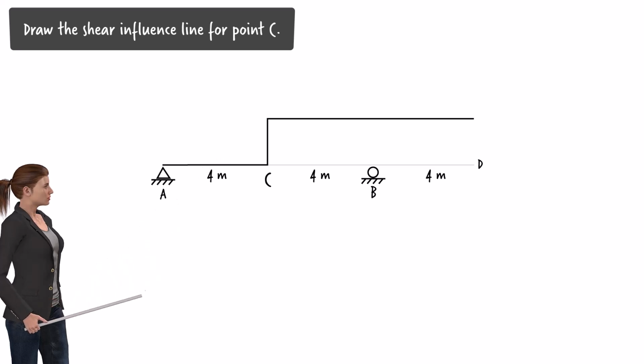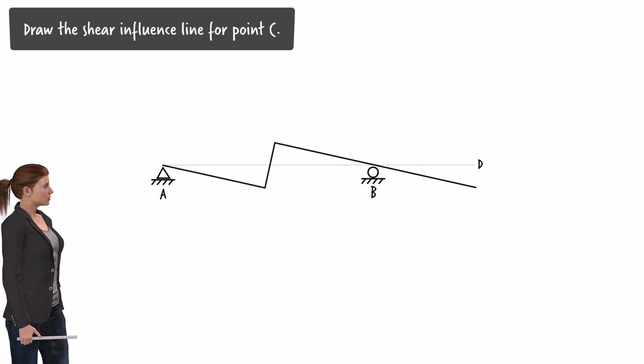Needless to say, this configuration does not satisfy the beam's boundary condition at point B, as the beam cannot have vertical displacement at the roller support. To correct this, we adjust the diagram by rotating and shifting it vertically. In this case, rotating it clockwise ensures that it rests on the pin and roller supports at A and B, thereby satisfying the boundary conditions. Here is the resulting shape.